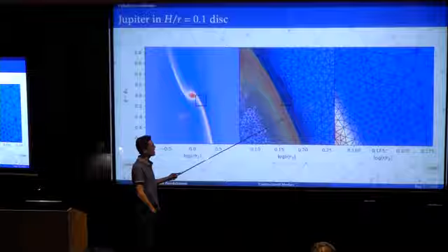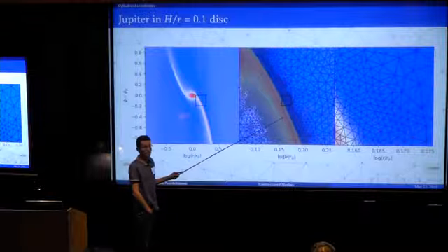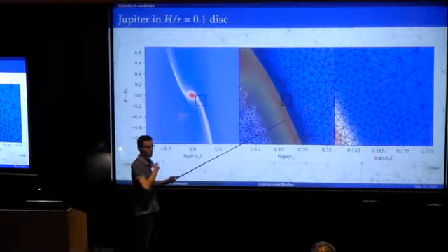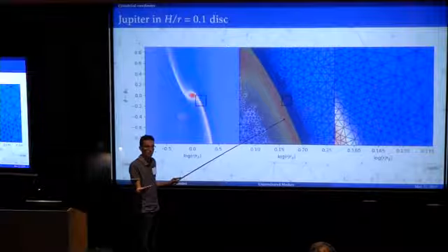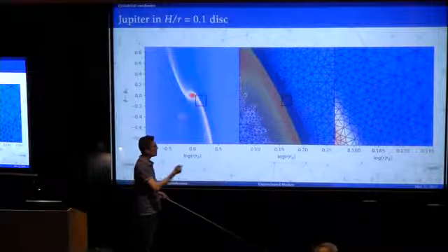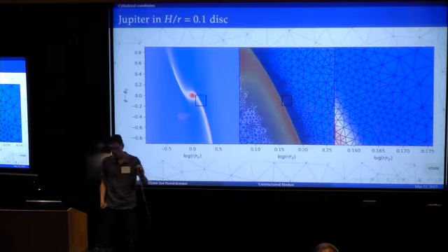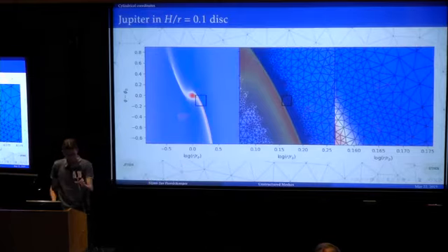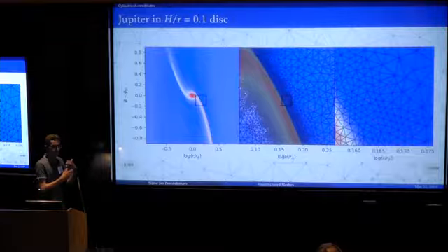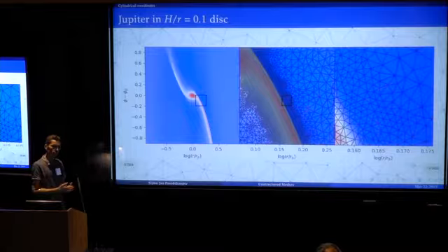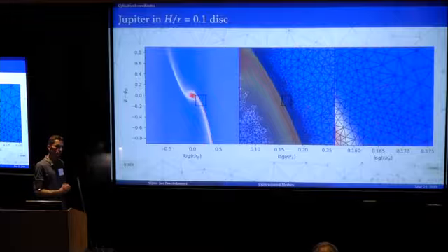But what you do is add points if necessary, and you can also remove points if you don't want them anymore. But they don't have any velocity themselves. And that way, this comes back to the quality of the mesh. That way we can guarantee that the mesh doesn't become distorted. So this is one of the reasons I'm not a big fan of moving these things around.